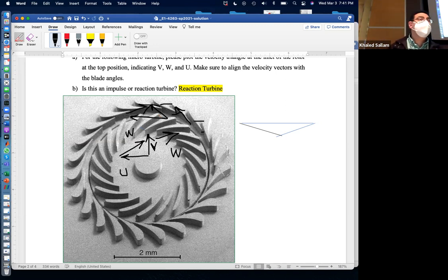The stator of a nozzle comes first and it reduces the pressure and increases the velocity. The stator of a compressor comes next after the rotor, and its point is to reduce the velocity and increase the pressure. And in both scenarios, the rotor itself doesn't do anything except extract V theta. That is the currency in the rotor. And the stator, and sometimes the rotor, deal with pressure too. Right? In the action rotor, they also increase or decrease the pressure by the passage.